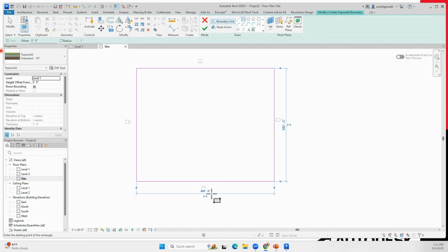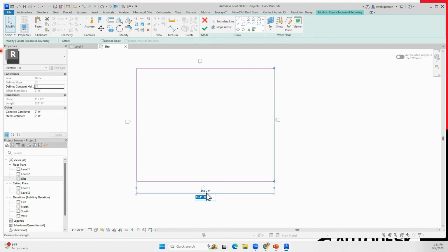He says yes. It's coming from a CAD file? Yeah. Then my point of view is try to edit the CAD file in CAD before bringing it into Revit. Control that in CAD before coming into Revit.